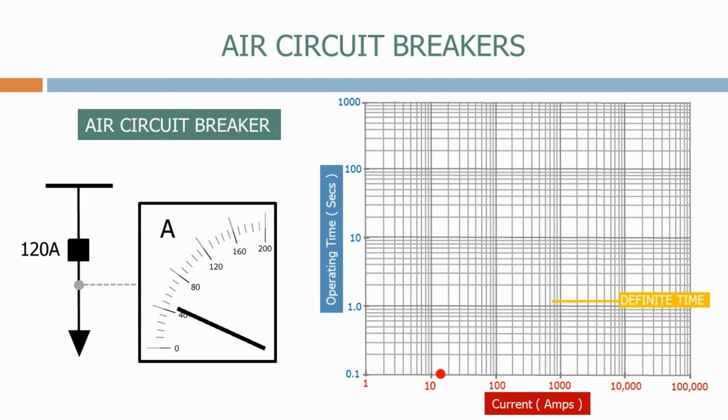The current now increases as the load increases, but the ACB will not react until the current exceeds the defined setting. Once it does, the circuit breaker reacts in the set time, removing the load from the system. The definite time curve is a very useful feature and is normally set to a level that protects the integrity of the cable and bus bars connected to the feeder.